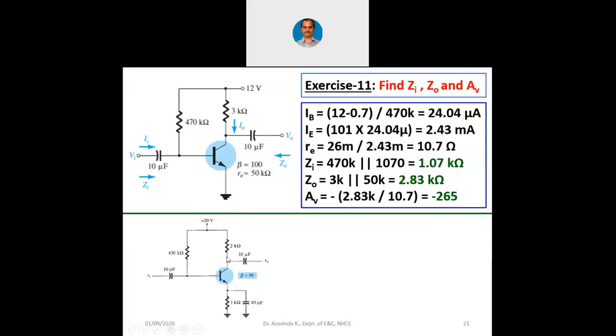Now whatever circuit you are seeing here at the left side is basically emitter bias, which we had seen earlier. The Q point of this emitter bias or self bias is more stable than that of the base bias or fixed bias. If we go for AC analysis of this circuitry, you can compare the upper circuit and the lower circuit together. There is an RB, here also there is an RB, there is an RC, here also there is an RC, there is a blocking capacitor and a coupling capacitor. In addition, there is an emitter resistor here in the emitter bias circuitry.